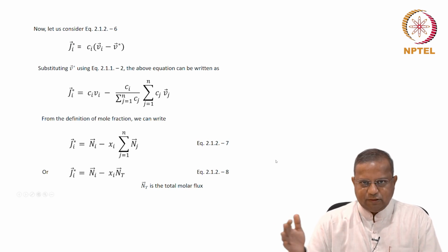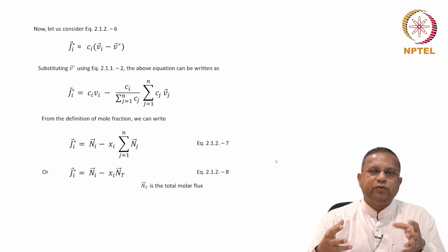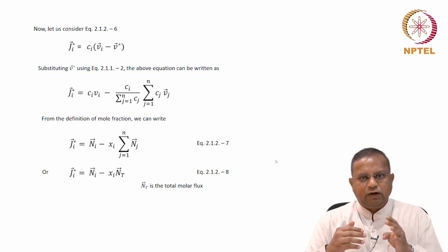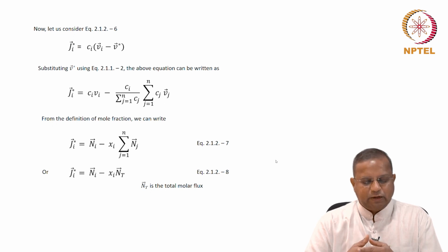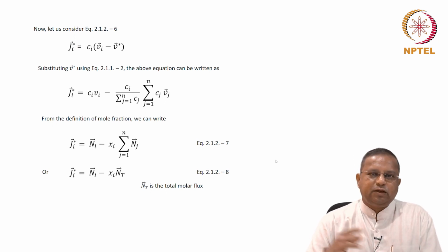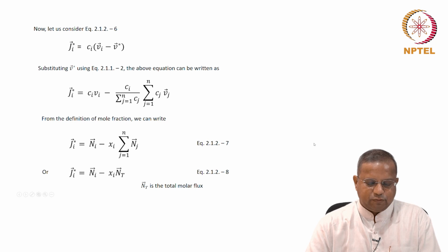However, we said throughout this chapter, we will consider only diffusive flux, only the flux that arises out of its primary driving force, a concentration gradient, and therefore you don't have to worry about the convective bulk motion and so on and so forth.